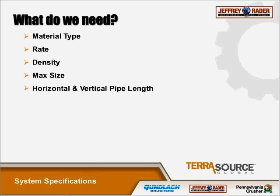We need to know the horizontal and vertical pipe length. We do not need to know an exact layout. We really just need the overall horizontal distance, the overall vertical distance, and the total degree of bends. Don't need to know there's 90s. We just need 360 total degrees, and we can get a very close estimate to what you need.